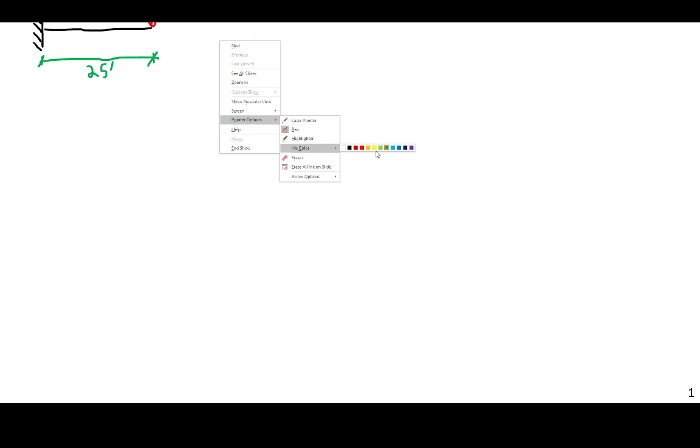Basically, I'm going to go through the full lateral torsional buckling calculation, including calculating CB. In this example, I am not going to assume CB is equal to 1. That is a conservative assumption we can make, but often it is way too conservative. So I'm given that we have this beam here, and I'm also given what it is.